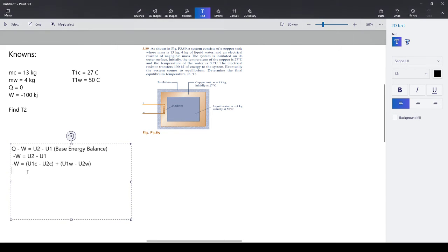So how we're going to do this is we have to go and find the specific heats, because I'm going to write the equation the way that Tanner, I think, said. Really quickly, this is what he's saying. The equation for specific heats is m c. If you want this in terms of total energies, you have to multiply by a mass, and our work is in kilojoules, so we need it multiplied by a mass. So m times Cp of C. This is the mass of the copper times the specific heat of copper times, I'll do this again, T1 copper minus T2 copper, right?